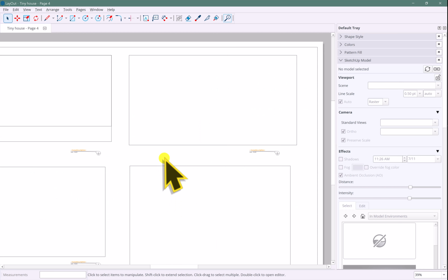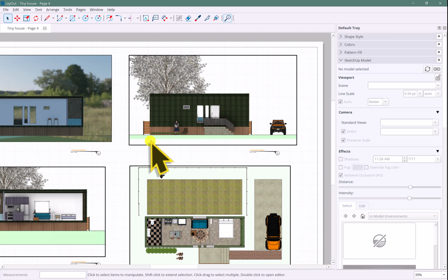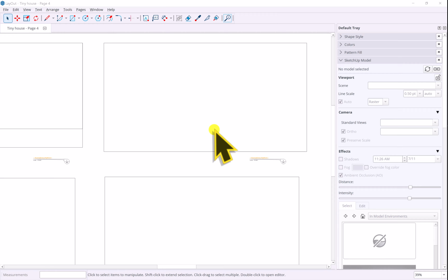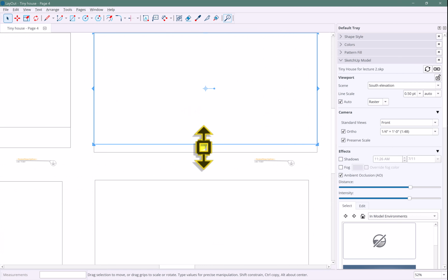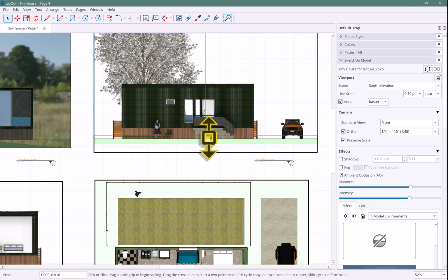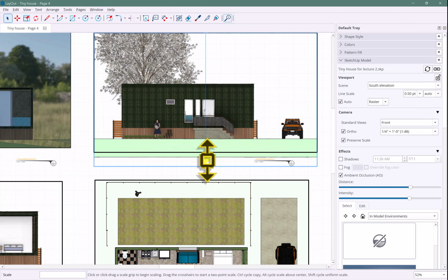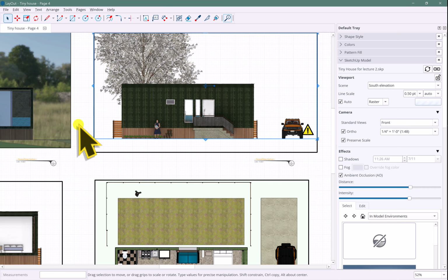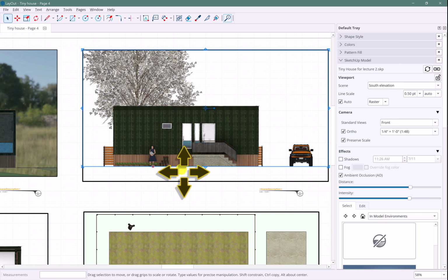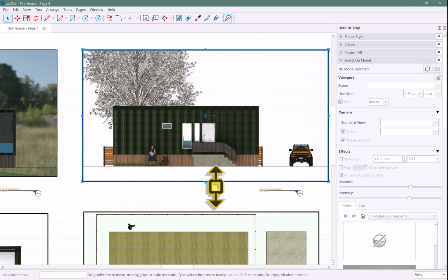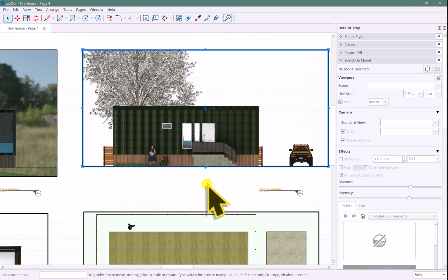And same here, you want to align something with the plan, and elevation would be great. So you can also draw yourself reference lines as well. Lastly, the elevations are a little different because, first of all, exterior elevations, if you remember, we crop them to the ground. And to make that work, sometimes you have to kind of move the crop up and down because it's forever snapping to stuff. And then we could use this outer boundary here to get ourselves a nice, neat elevation.